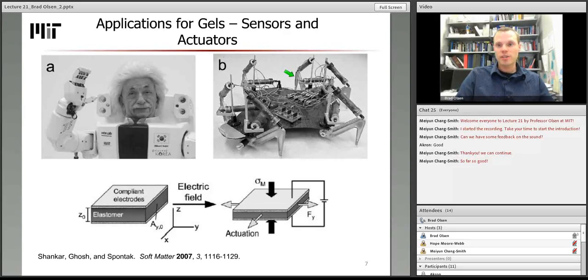And because the material is a gel, you have a relatively small amount of force required to do the deformation, and you essentially create a soft actuator, which can more accurately or more faithfully reproduce the facial expressions and motion of things like muscles. So these soft actuators are very, very interesting for when, instead of actuating large or heavy loads, we are trying to do fine motion of, for example, soft structures.